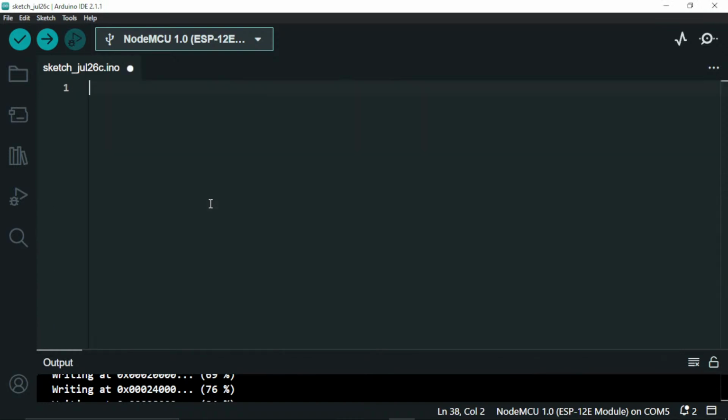So now let me erase this again. Now we can move to the next thing, which is displaying custom characters. In a 16x2 LCD there are actually 32 blocks where you can display characters, and each block is made out of 5x8 tiny pixels. You can display custom characters just by defining the state of each tiny pixel. For that you can create a byte variable to hold the state of each pixel.